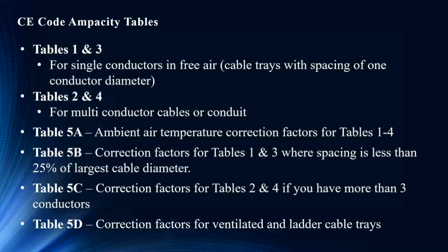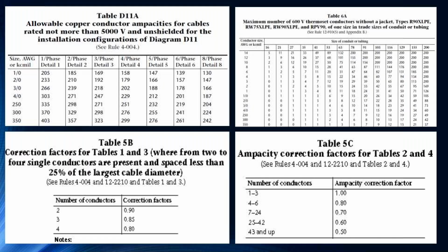The tables noted over there, I'm trying to bring up some pictures, so if you can bear with me. So these are the tables. As you see, the appeal and convenience of this method is that it allows engineers and technical designers to easily look up the corresponding cable sizes based on the listed ampacities rather than using the actual Neher-McGrath method to calculate the respective values.